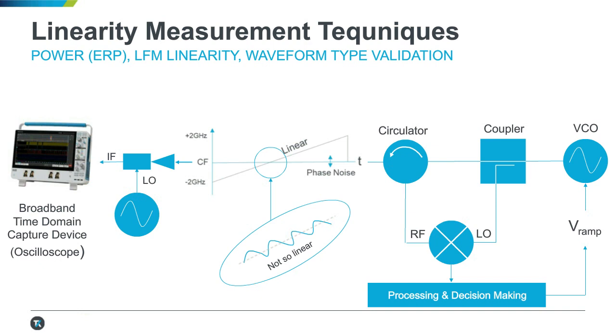But if that chirp isn't linear, i.e. if it doesn't sweep in a linear manner, you're going to have problems, and I can show you on the diagram right there in the center, if we zoom in to what looks like a linear chirp. In reality, at the end of the day, an automotive radar will be optimized for cost, so it won't be like a military radar. It will use some basic components, and there will be some compromises, and the chirp may be not so linear.